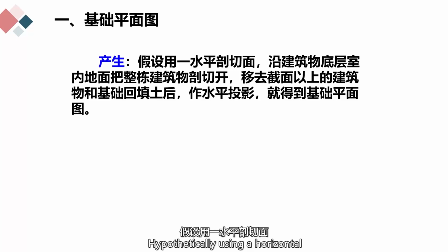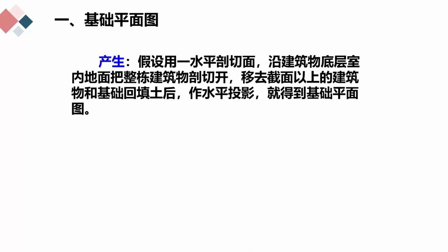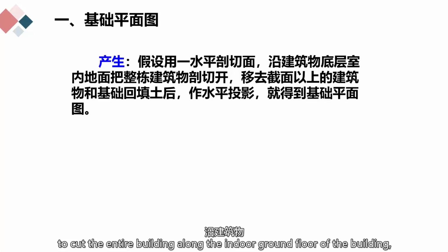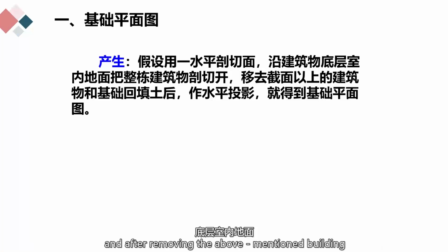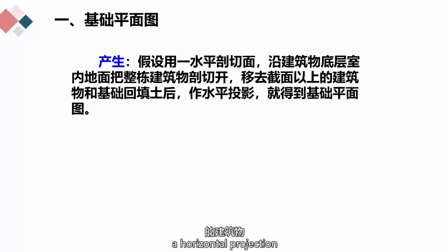First, foundation plan. Origin: hypothetically using a horizontal plane to cut the entire building along the indoor ground floor of the building, and after removing the above-mentioned building and foundation backfill, a horizontal projection is made to obtain the foundation plan.